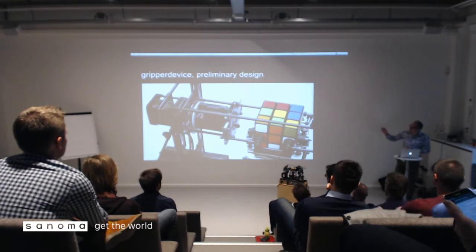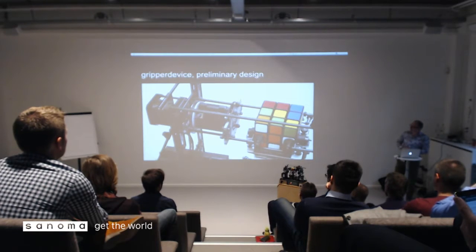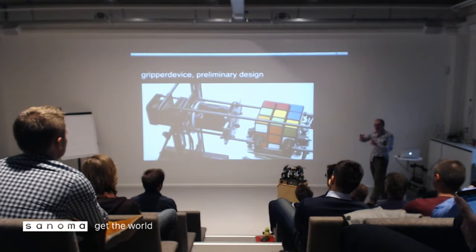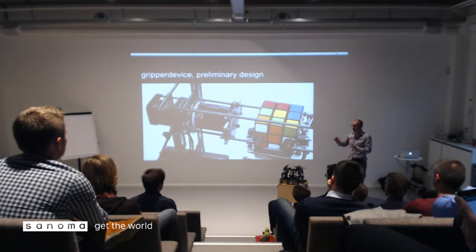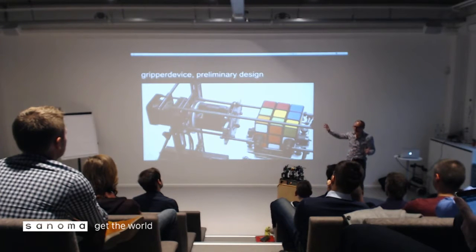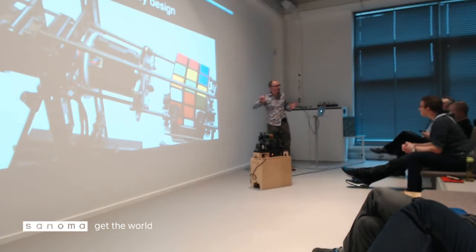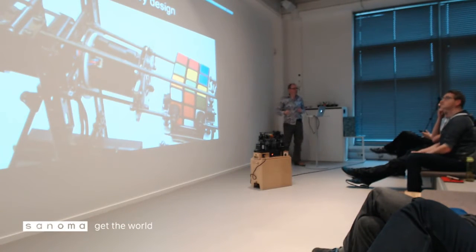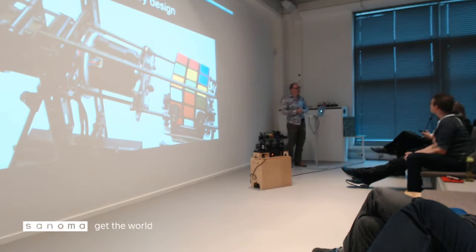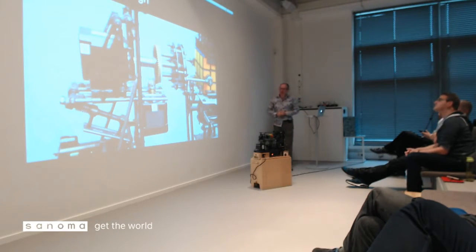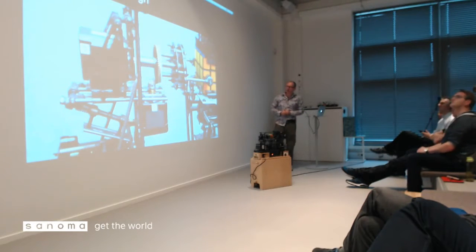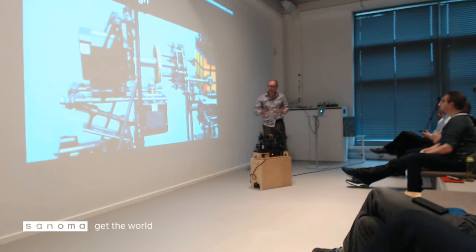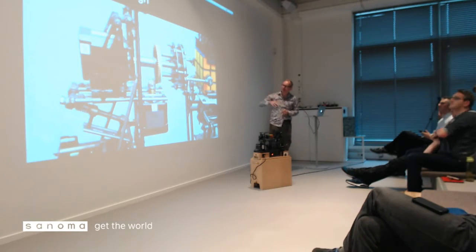Well, in this concept, I had one motor in the satellite of the gripper, which indicates that the wiring is also incorporated in the satellite. Well, that makes it a bit tricky, because you can only rotate the gripper to a certain extent. Let's say 2 times 90 degrees, and then you've got to rotate it counterclockwise. Otherwise, your wiring will be just blown off the motor, and then you're just finished. So actually, I changed that concept without changing the whole machine, by the way. I only had to change the device of the gripper.